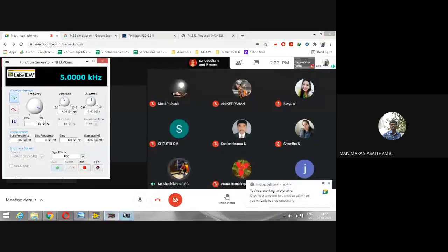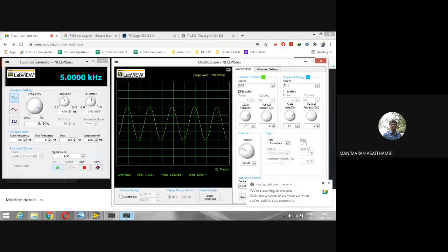So now, if you see there, I still have a function generator oscilloscope. Now I have a diode connected with me, and I have a resistor also with me there. So what I'll do is, I connect the function generator input to the diode input line. I am connecting the function generator reference to the resistor end. I am connecting one wire to the oscilloscope input from the diode output end, other end.